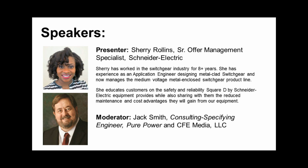The other thing to consider is, do you need that very robust ANSI standard, C37.13 or 13A, that's specific for generators? Typically you'll see that specified if you have a very large, very mission-critical generator where the breaker would have to interrupt a lot of X to R ratio. Without getting into the details, most people do use general-purpose circuit breakers for generator applications. Without getting too specific, I would say absolutely 90 to 95% of the applications for generators could be considered for fixed-mounted, as you would with withdrawable.